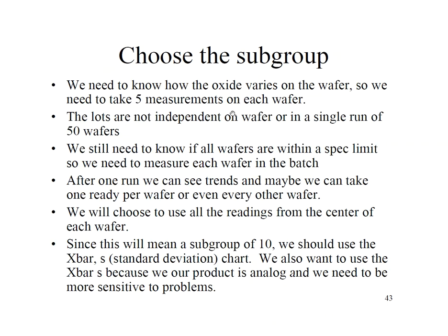So we're going to measure oxide thickness across the wafer, subgroup 5, because we've been doing that a long time. Now, each run in the furnace isn't necessarily independent. Those wafers aren't independent of each other, right?